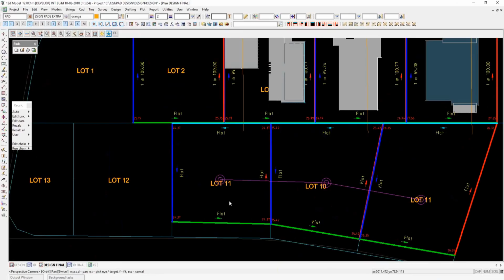You've got to think about it as a surface, and if you're able to create an L shape, the pad option will work happily with that. Obviously, it has to have at least three points, but the whole process would be to just create and treat them as individual surfaces that would relate to each other at certain points. So if you had a ramp coming up to here, then obviously the points here and here would be the same on the ramp as they would be on the other pad.